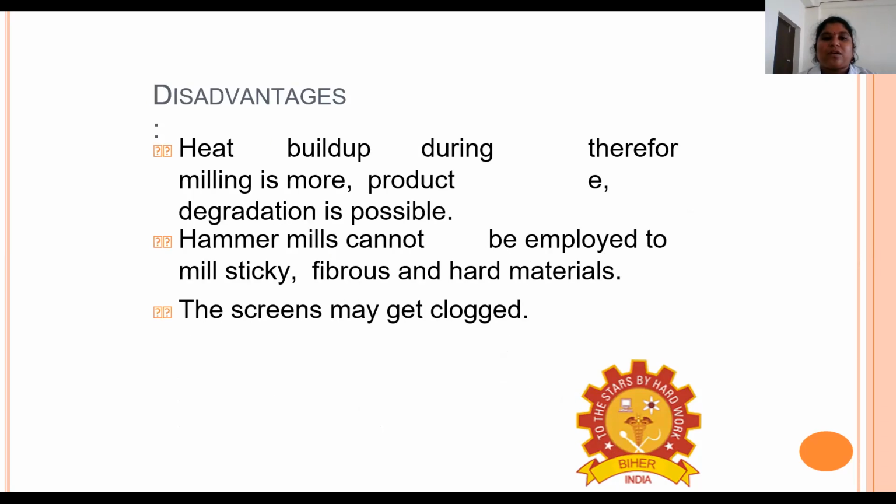What are the disadvantages of this hammer mill? Heat build-up: heat is produced during the process, and it cannot be used for sticky, fibrous, and hard materials because the screen may get clogged.